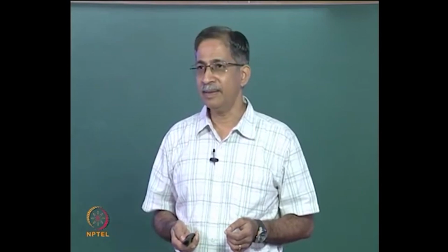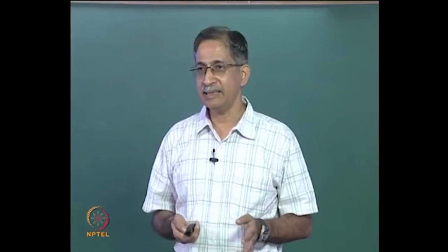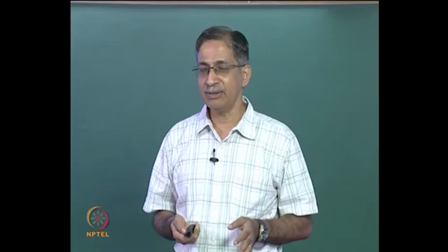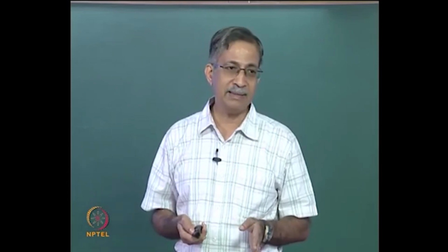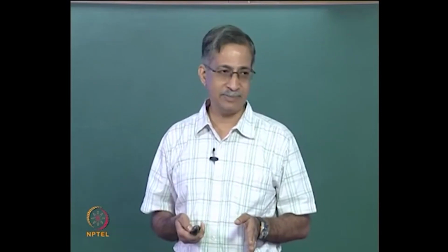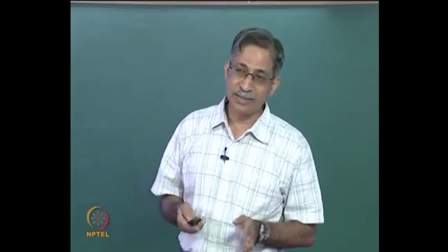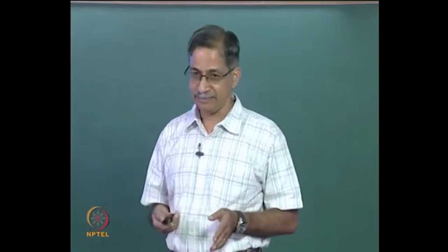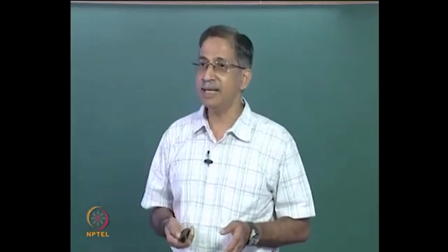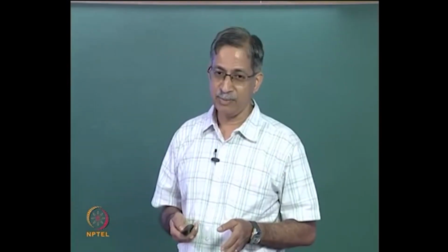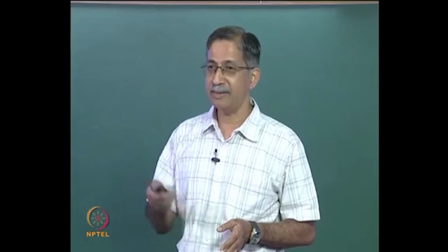Now work is given by the axial force N of x and the local elongation at that point, which comes when you integrate the strain. The strain is u dash of x, du by dx, and so this is the expression for the internal virtual work, and if you invoke the expansion of that integral,